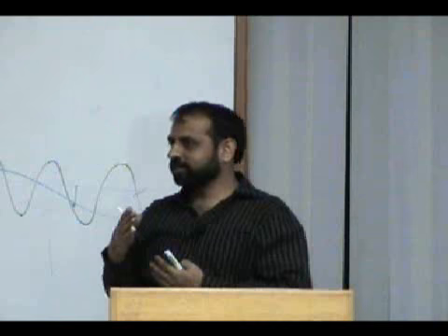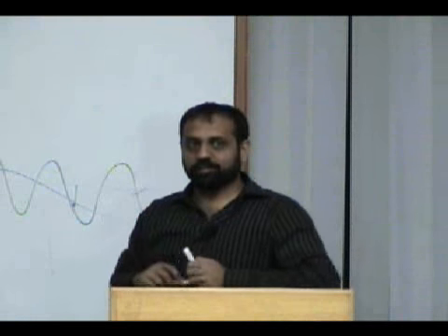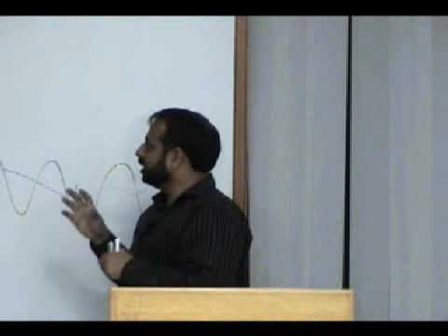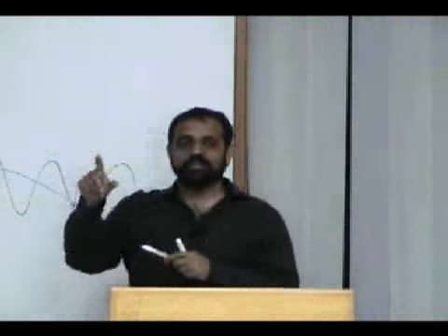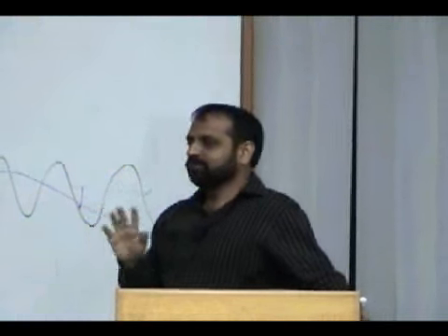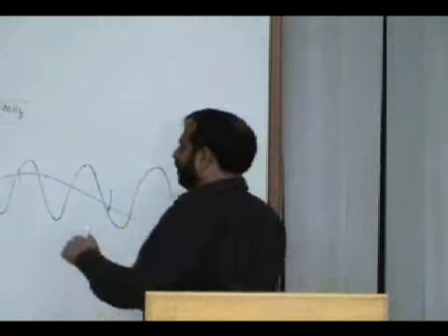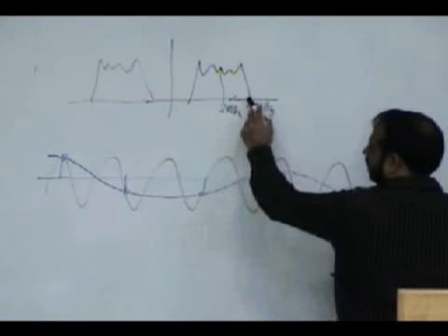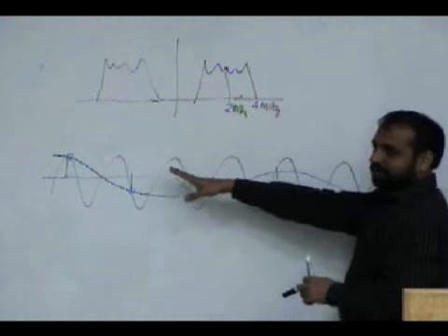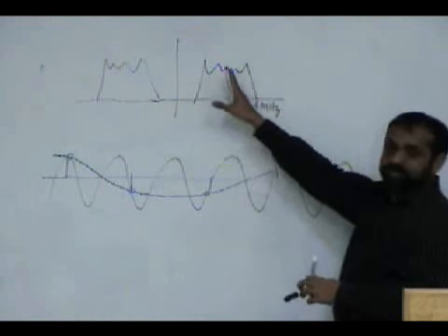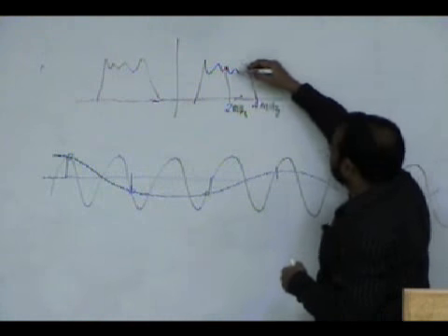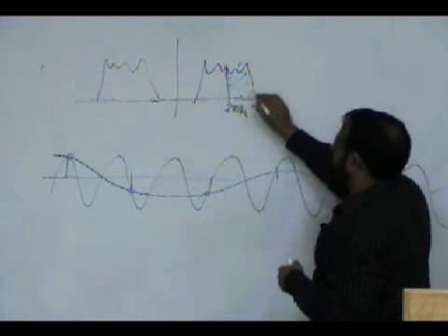But the problem is, if you are not cautious about this fact, you need to know that just sampling a signal which has higher frequency content at an inappropriate rate will not only make you lose this, it will also in fact come back and affect a frequency. You are not only not sampling this appropriately, you are sampling the entire half of this band inappropriately.